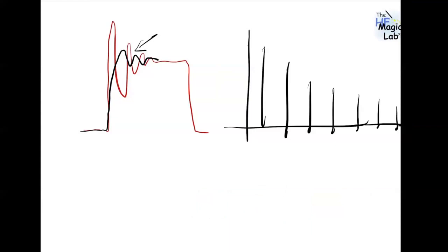The ringing, instead of this envelope, will create this mountain. And this mountain is what you probably will be able to solve with the snubbers, but not the amplitude of the harmonics. The amplitude of the harmonics must be reduced in other ways: reducing or increasing the switching times, or with spread spectrum, and so on.